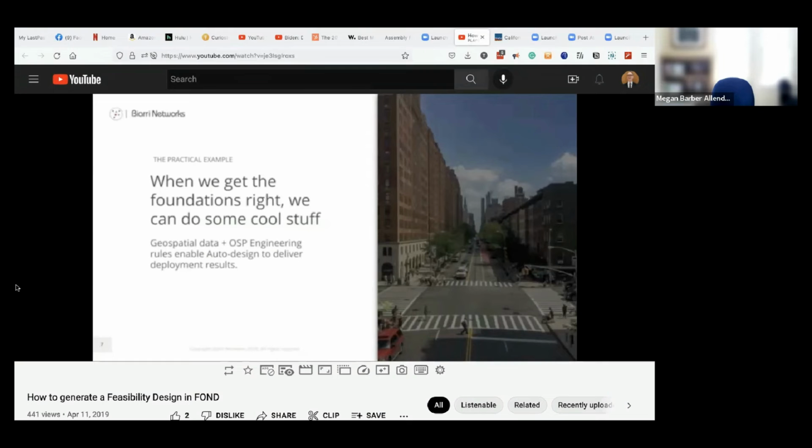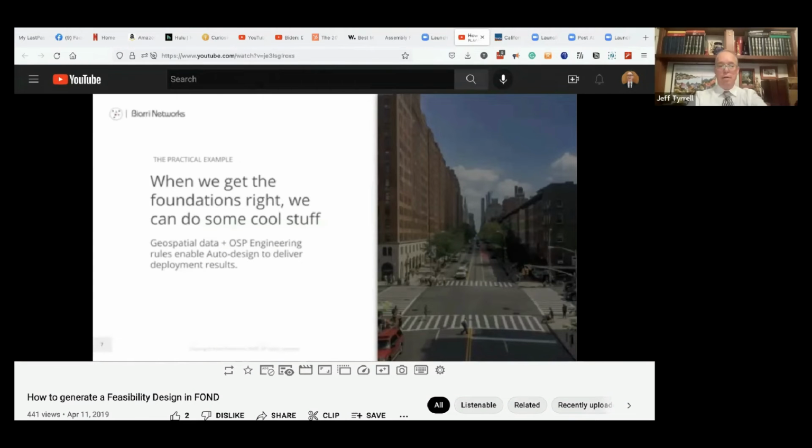In that example, I just used underground data. Often that's all that's available. Aerial, strand, and pole data isn't always available, and so sometimes street centerline designs can be a good way to get started. They can be used as a basis for a walkout guide or for estimating footage. You can use that design to walk out and collect information on where your poles are.